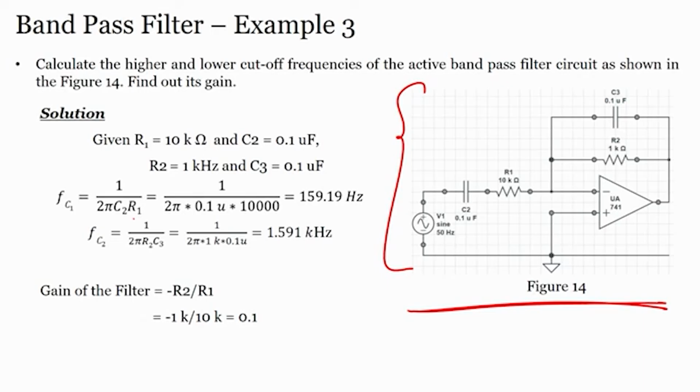And in the op amp, you can use a non inverting operational amplifier or an inverting operational amplifier. So, by using the non inverting and inverting operational amplifier, your formula for gain would be slightly different. For the inverting amplifier, it will be minus R2 by R1 or minus RF by Rin, and for the non inverting amplifier it will be 1 plus RF by Rin, right. Otherwise, the things remain super simple. For the frequency formula, always remember it is f equals 1 upon 2 pi RC.